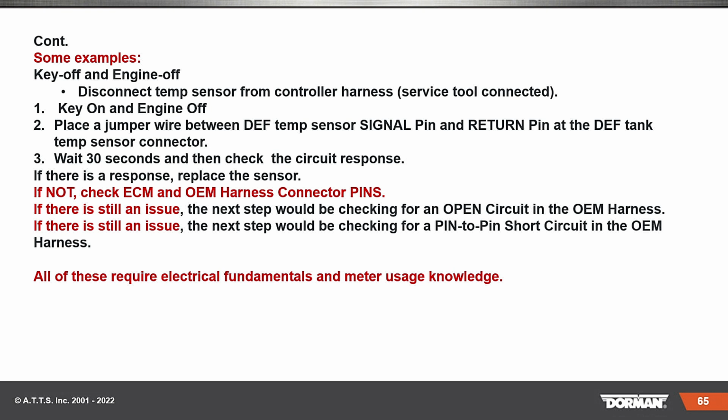If there's still an issue, next step would be checking for an open circuit in the OEM harness, because don't forget, you're talking between the actual engine guy and who put that aftertreatment in there. Is it the OEM, and so on? But the bottom line, whatever you do, all of these will definitely require electrical fundamentals and meter usage knowledge, guys.